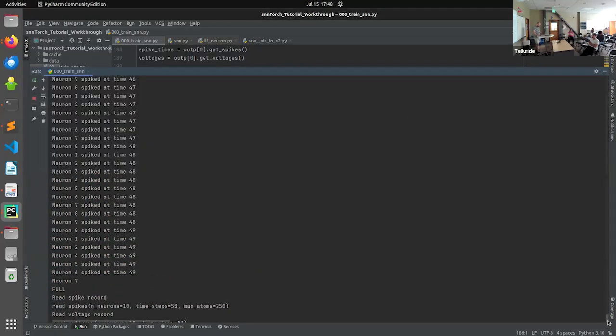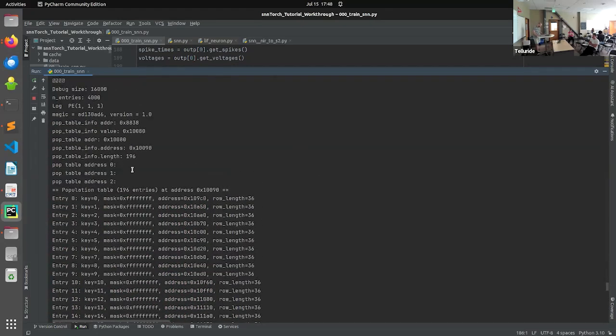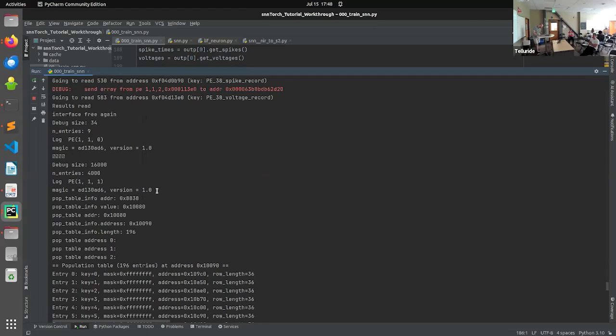And what you can see here now is that we're executing it on SpiNNaker 2. In terms of learning, you've got things like e-prop, EventProp, that we also implemented in Telluride, and synaptic sampling, DEEP R, so a couple of the verified ones, that will run on chip. Yes, exactly. Okay, that's nice. Plus things like what we recently did with block local learning, which is also going to be implemented in the future. So you can actually do serious DNN training, also multi-layer training there.